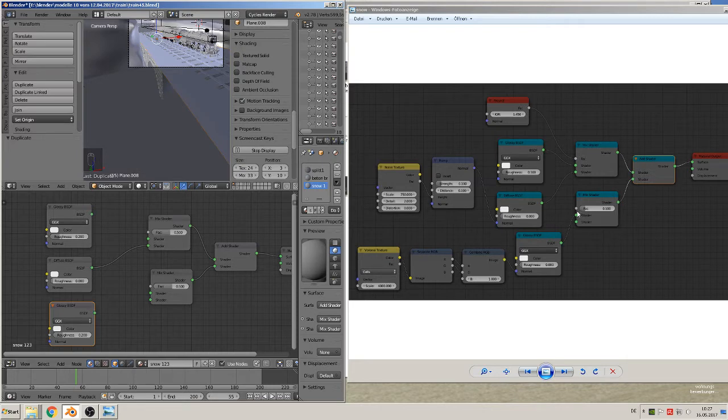This down part, you see it here, will be in that mix shader. And look at these values there. You must have the same. Here is 200, there 0. So we make here a 0. Good. You see the diffuse shader, it is 0. Wonderful. You see this glossy shader, here this glossy shader is 0.1. So we go in here and type 0.1. Good. And this glossy shader goes in the middle, so we make it in the middle.